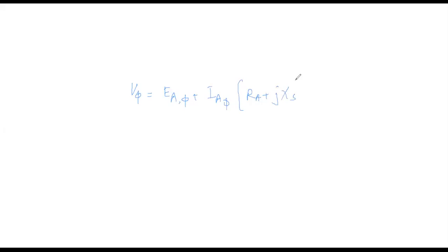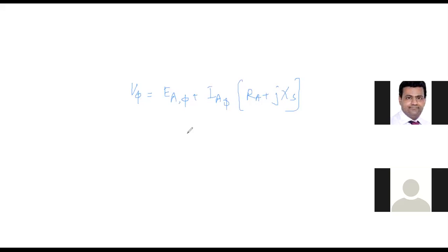So this equation is always written in phase values, and the open circuit characteristic would mean that for a synchronous generator, if you do not attach a load and you give it some excitation and you rotate the rotor, then this much EA would be produced. So the same value of EA can be plugged into the equation for the synchronous motor when you give it a certain amount of excitation. So the EA values could come from the graph. Let me go back.